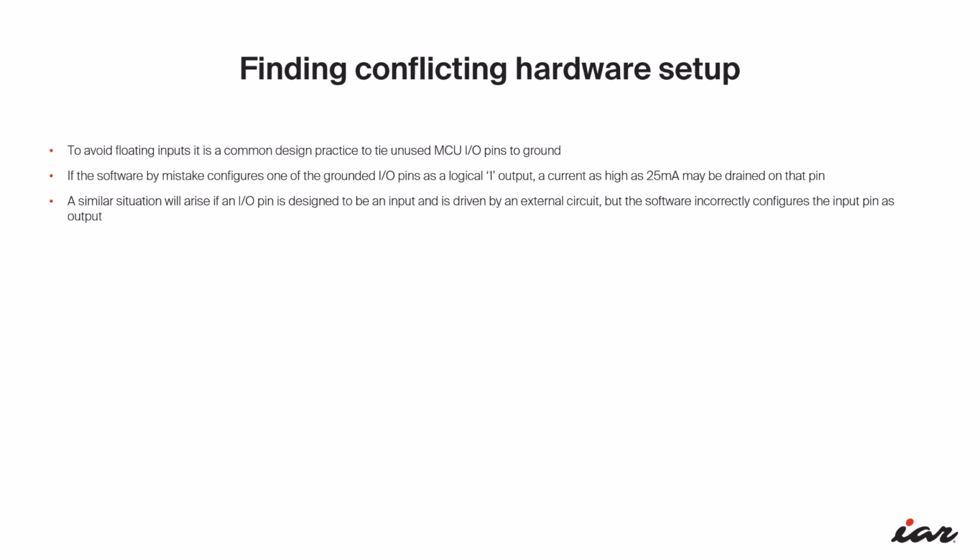A similar situation will arise if an I/O pin is designed to be an input and is driven by an external circuit, but the software incorrectly configures the input pin as output.